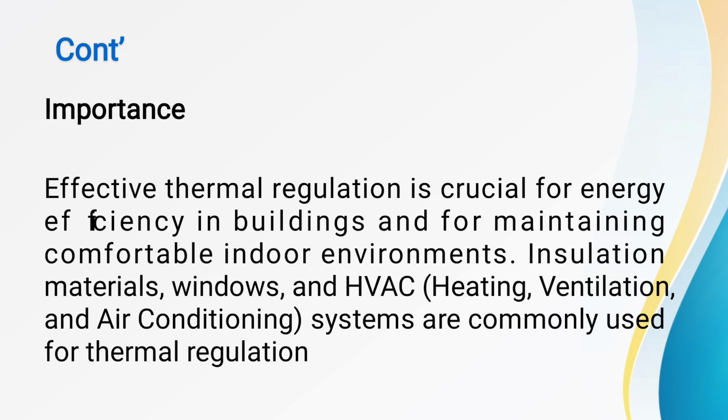Then you also have some other materials that insulate a building from high temperatures, especially the materials that are used in construction of a roof. Then moving forward, we'll also look at the ability of a material to conduct heat, that is the thermal conductivity. Then we also look at the thermal mass. Thermal mass is the ability of a material to absorb heat, store heat, and stabilize the indoor temperatures.